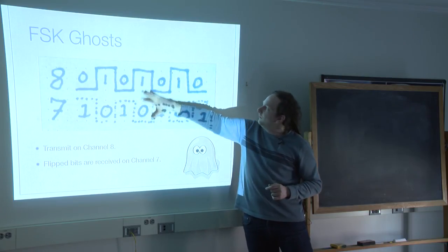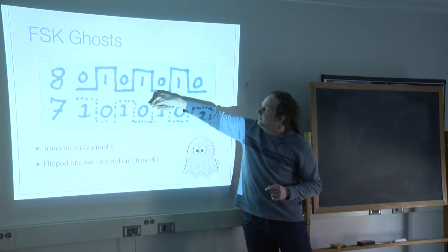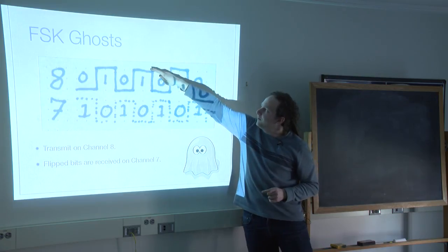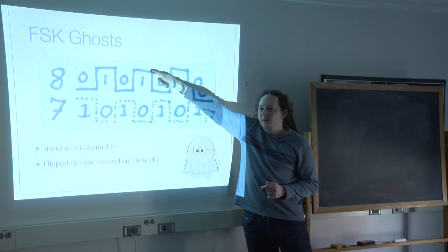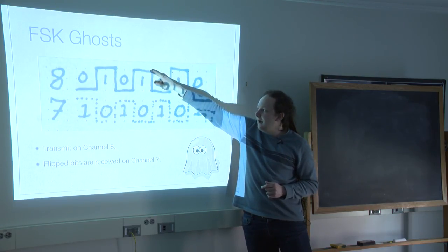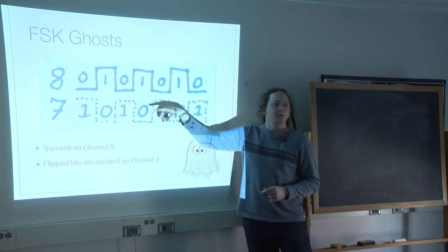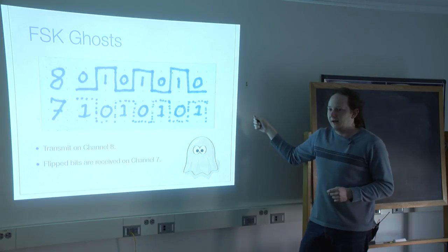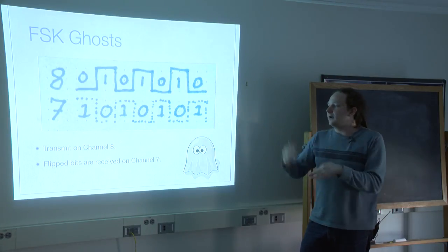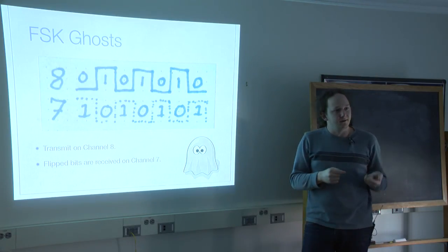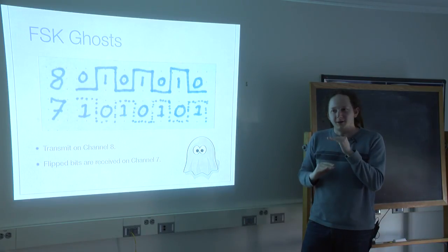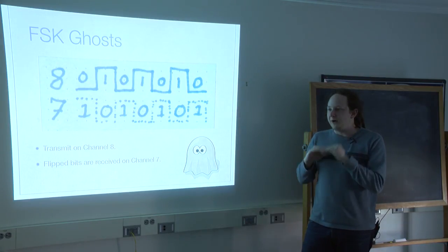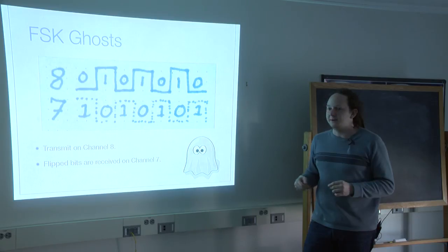And then when the legitimate one sends a 1, you see that as a 0 because the strong frequency is so far away that your receiver sees it as the absence of a strong 1, which it will automatically calibrate to be a 0. And in this way, just by inverting all of the bits and then hoping that the receiver is on just slightly the wrong channel, you can inject a message that was never intended to be transmitted.